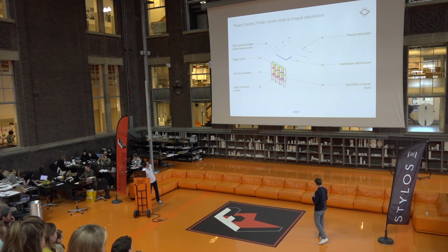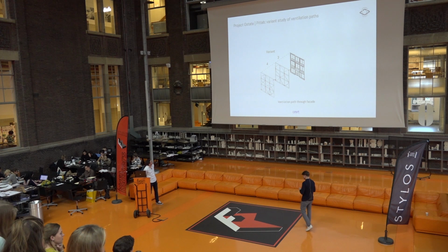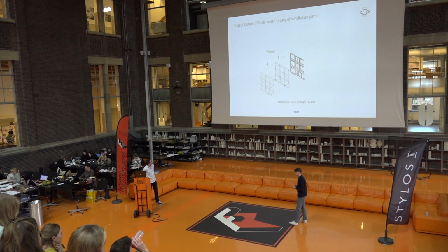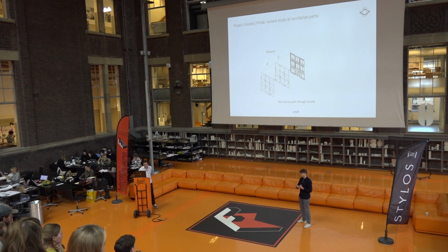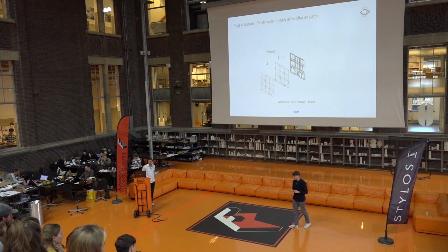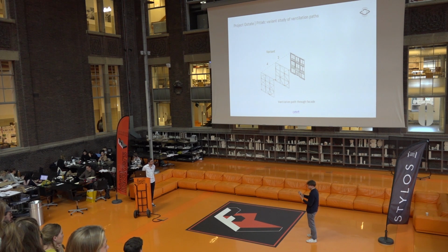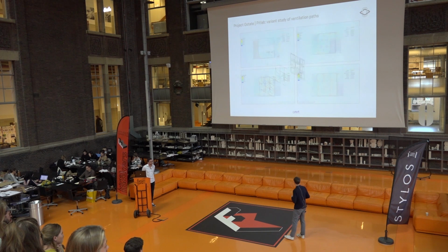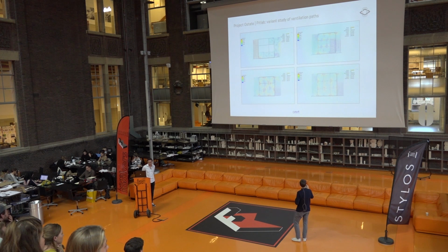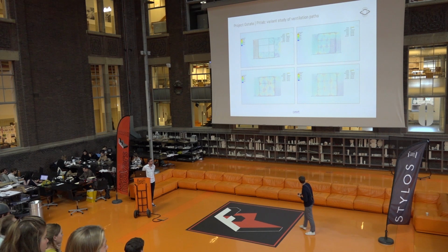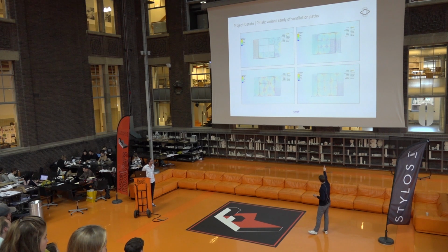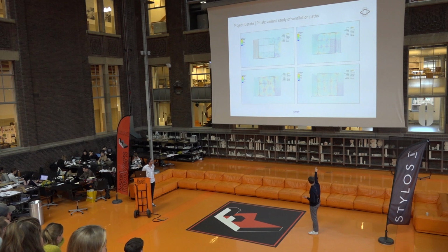First we started with the ventilation test throughout the facade, to see if we could reach an optimum of getting air divided as evenly as possible through the whole double facade, to give the plants a healthy environment. This is where we linked Flow Design to Grasshopper and the whole model, and we optimized towards the one right below.